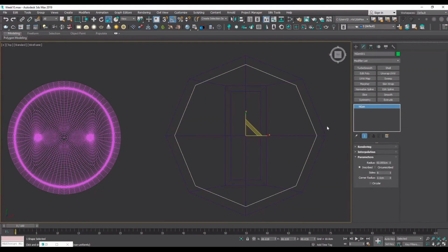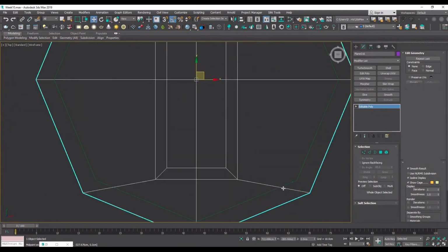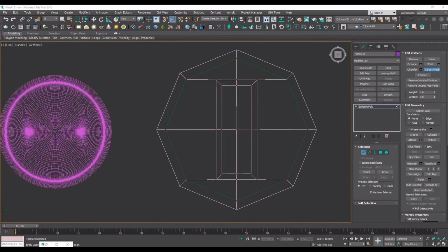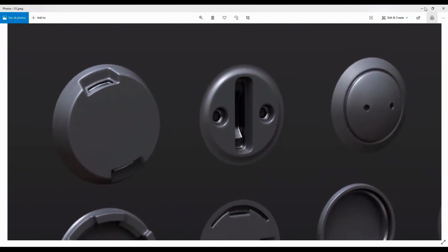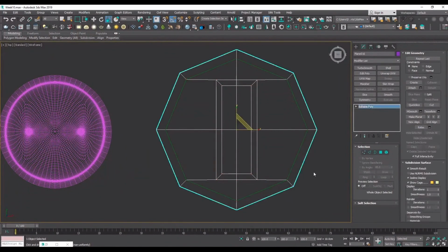So I now scaled down our reference n-gon a little bit more to create the safe loop we talked about in earlier examples and basically start to cut its shape again with the cut tool that we have. And now I just move the vertices and snap them to the place I want. So let me bring the reference. I need the second circle for the outward shape. The thing is that I will later extrude what I have here, and let's start the inner part now.